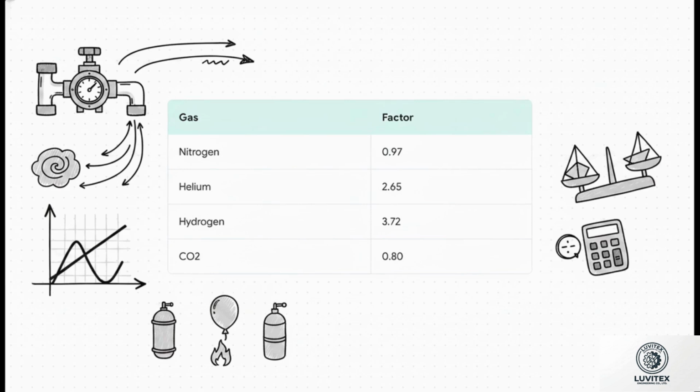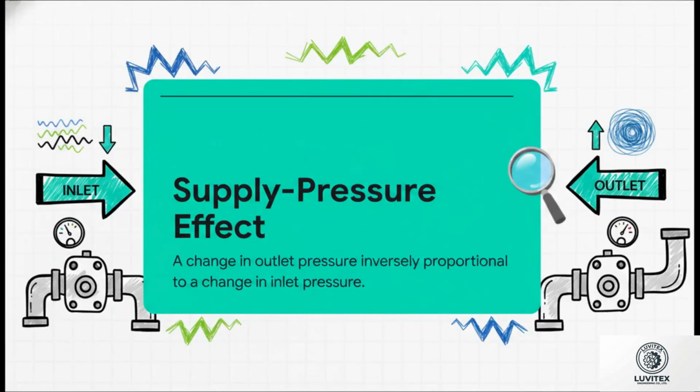Manufacturers usually generate their gas flow curves using nitrogen and their liquid curves using water or hydraulic oil. So if you're running high-density gases like hydrogen or helium, it's going to severely alter your sizing. It'll force the regulator to open much wider just to maintain equivalent flow rates, which in turn causes a much steeper drop in pressure.